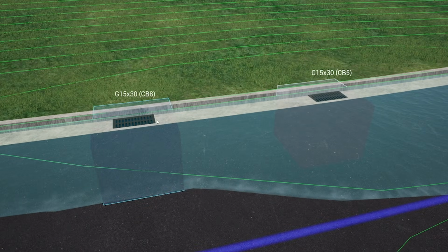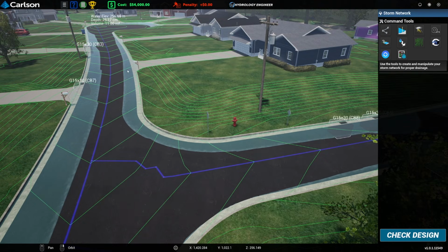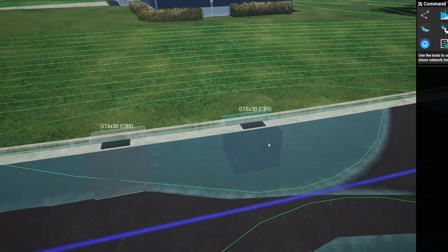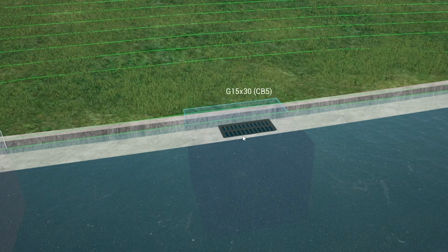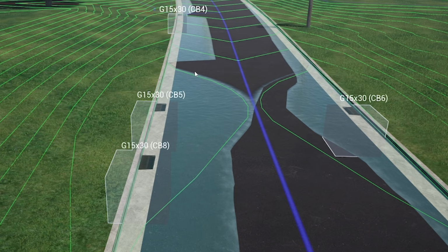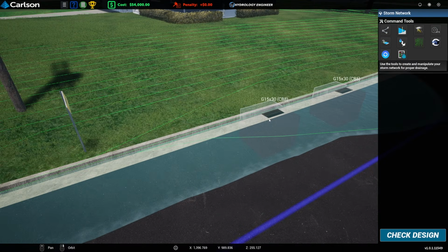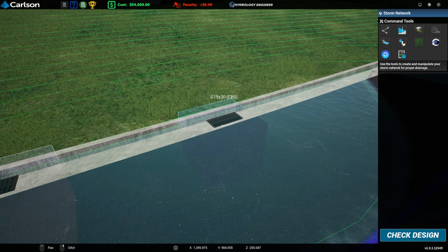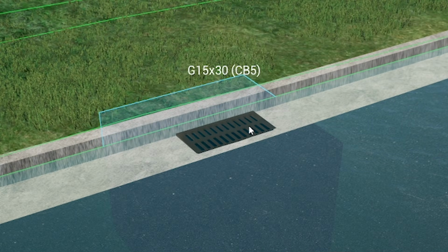Okay, you might be wondering, well, Matt, that's so close to the low point. Obviously, between the two, it's going to be a really low flow width, so surely I should move this gully up. No, you should always work from upstream, mostly because low points are the most important part of a drainage network. If this gets blocked, you can see you get a massive puddle across the entire road. That's completely flooded. Road gets blocked. So by doing your spacing from upstream, less water is going to go into this gully, which just means it has extra capacity should something go wrong upstream.